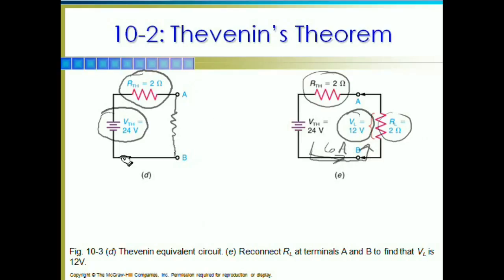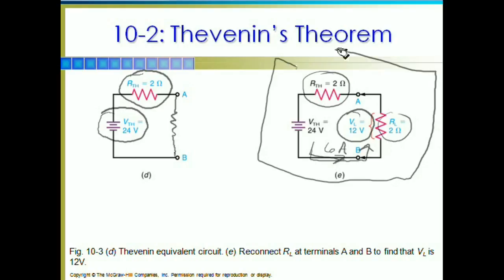So it made it quite a bit easier now. I can throw in any load here and quickly and easily calculate what my drop across that load is going to be by having first set up my Thevenin circuit. So let's do that one more time.